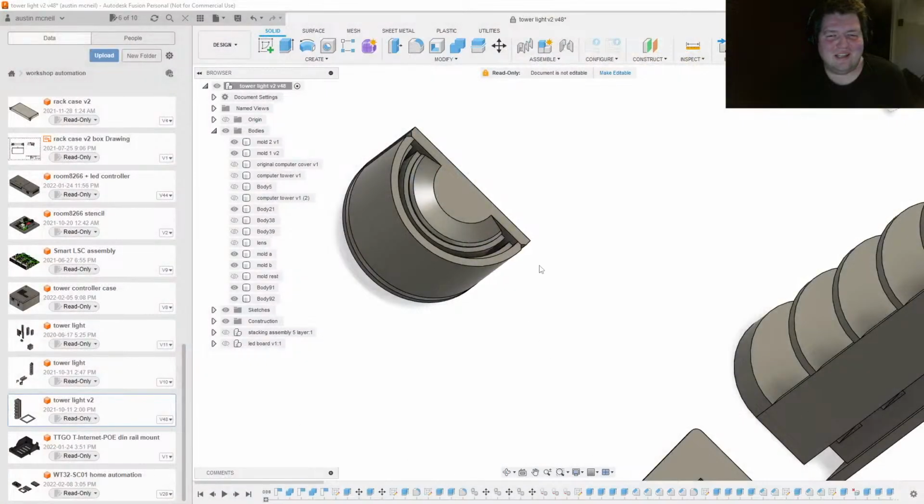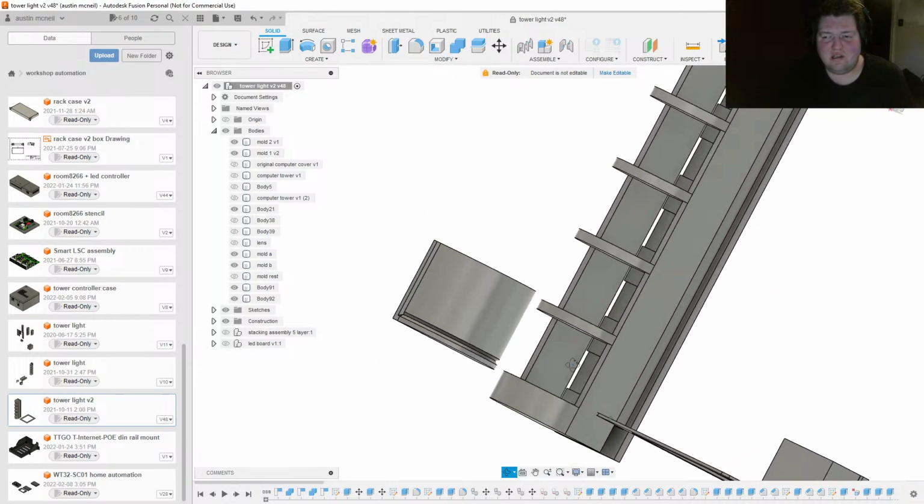I think I made enough molds to do a bunch of lenses at once, and then I think I made an adjustment because I realized the resin would sink a little, and I needed a way to help it actually go in this relatively small opening. So I made a new mold that made it easier to pour into. So I made this 3D printable mold so that I could pour epoxy resin that had some tint in it to make the lenses, and then it fits.